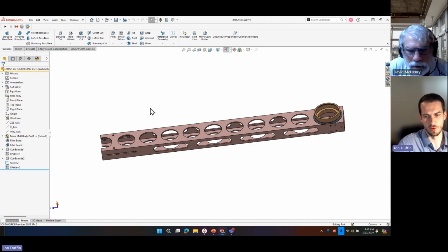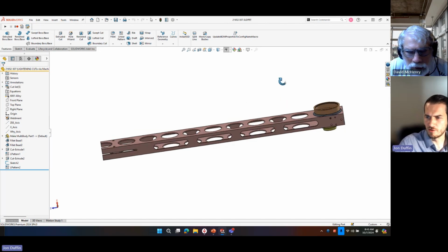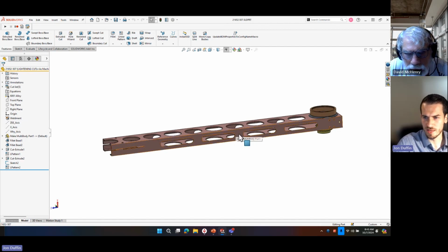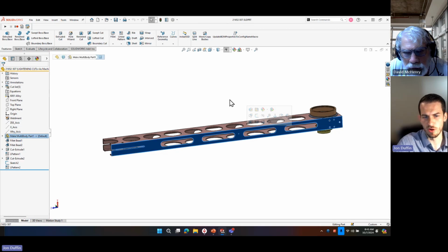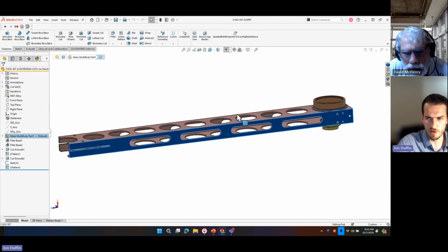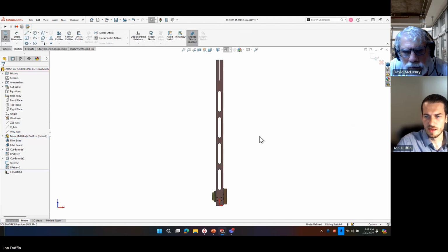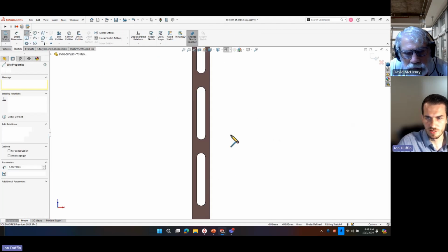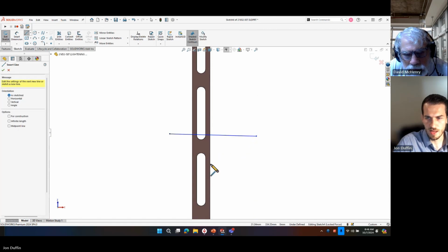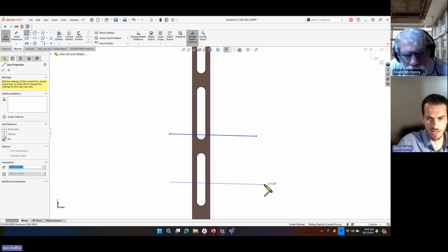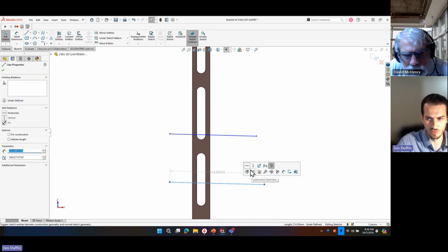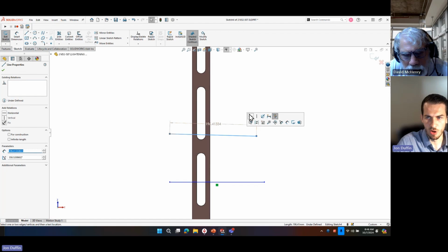Perfect. So very first, let's knock the first one out: being able to split that face using a split line. I only want to fix a little portion of here. Really what you do is make a sketch where you want that face to be split. So in this case, let me start a sketch on this face, and then I'll draw two lines arbitrarily on here. In between these lines is where I want the face split. Obviously, I just drew these randomly.